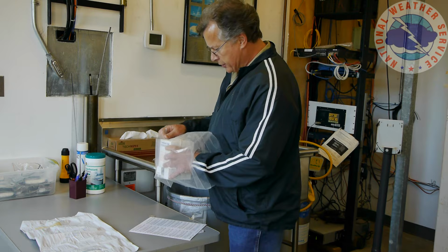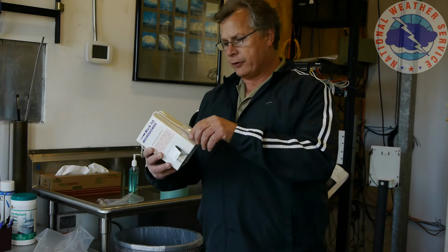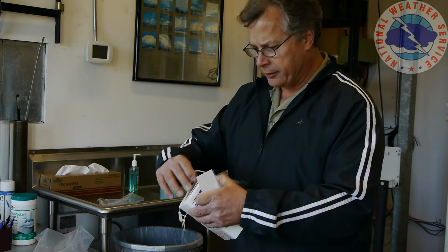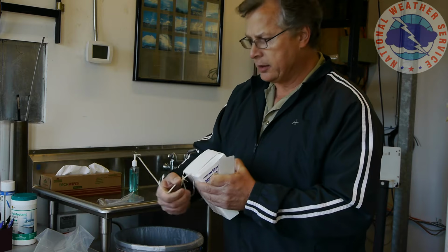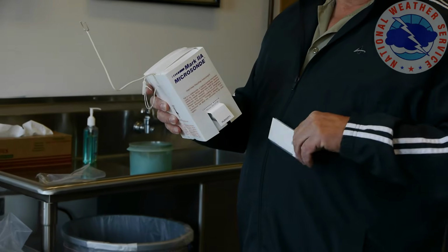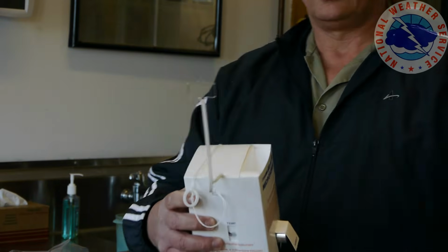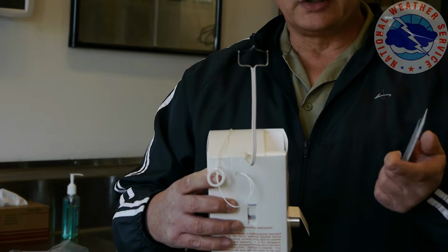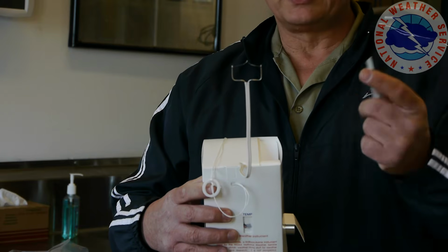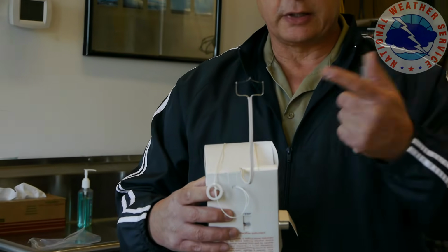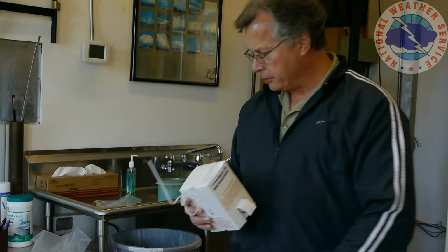and then we'll review the basic parts that actually take the measurements. The first thing I'll expose here is the thermistor. This is the device that actually measures the temperature. Voltage from the battery runs across the electrode on this thermistor. Changes in temperature alter the resistance of the electrical current, which is how it determines the actual temperature.